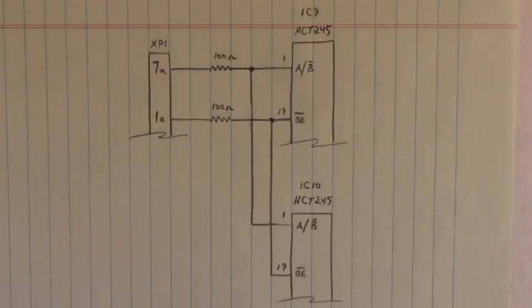Now here on the 2-each 74ACT245s, we have 2 control pins. Pin 1 is the data direction, whether data flows from the 8 bits of the A side to the 8 bits of the B side, or whether we have data flow from the 8 bits of the B side to the A side. Shoo! That's a tongue twister.